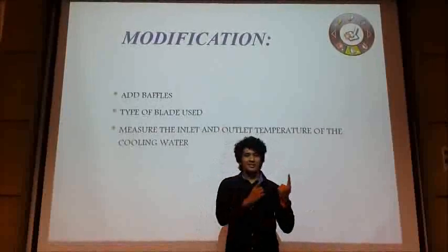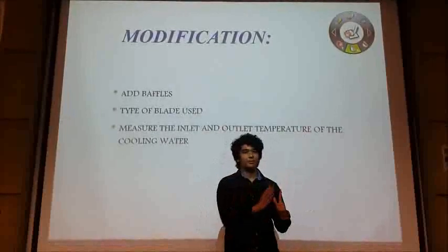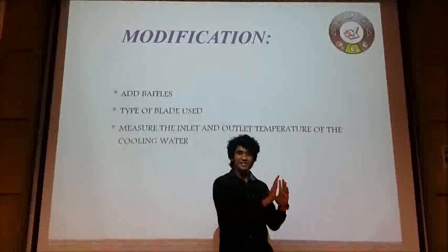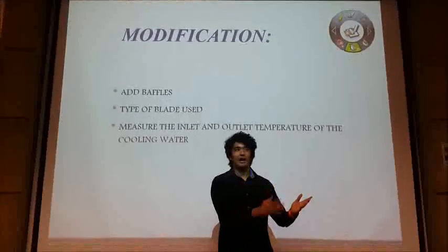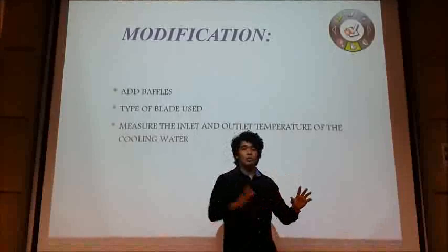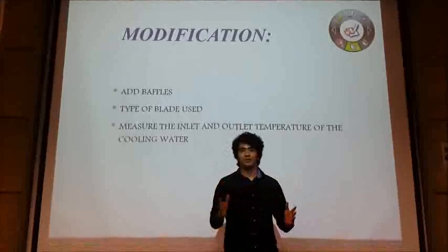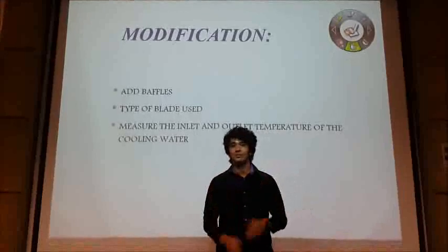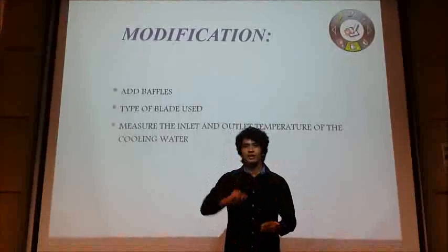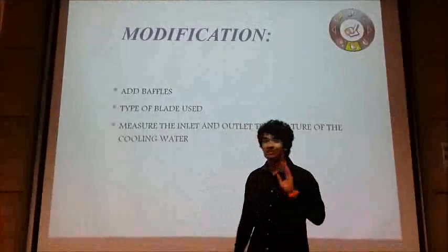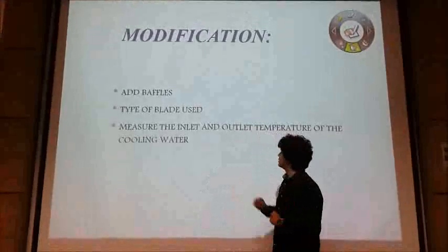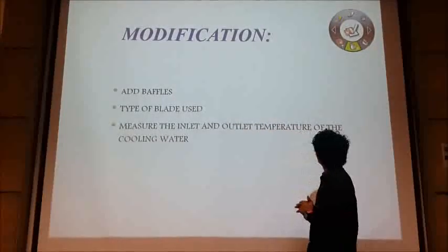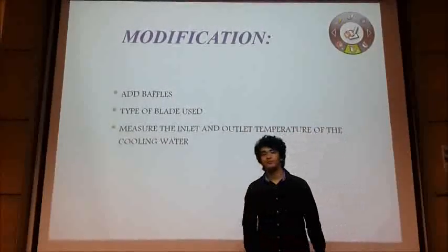So the reactants at the side of the wall will be reacted. It would not be stationary there and be an unreacted area. Almost everything will be reacted off the reactor at the same time. So the rate of reaction everywhere is almost constant. It's almost the same. Last thing is, we should measure the inlet and outlet temperatures of the cooling water.